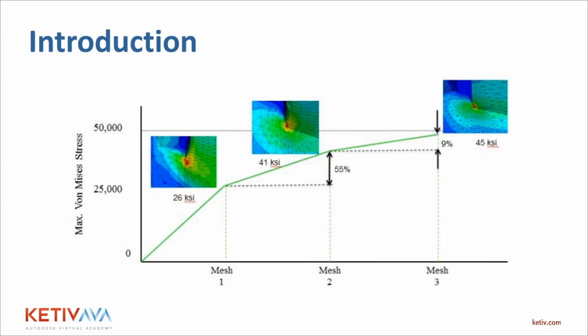Now, as a general rule of thumb, a higher element count is going to lead to greater solution accuracy. In most problems, however, refining the mesh beyond a certain point leads to very small, if any, changes in solution. This convergence is one of the primary means of actually verifying the results of an FEA study, and we'll look at that in short.